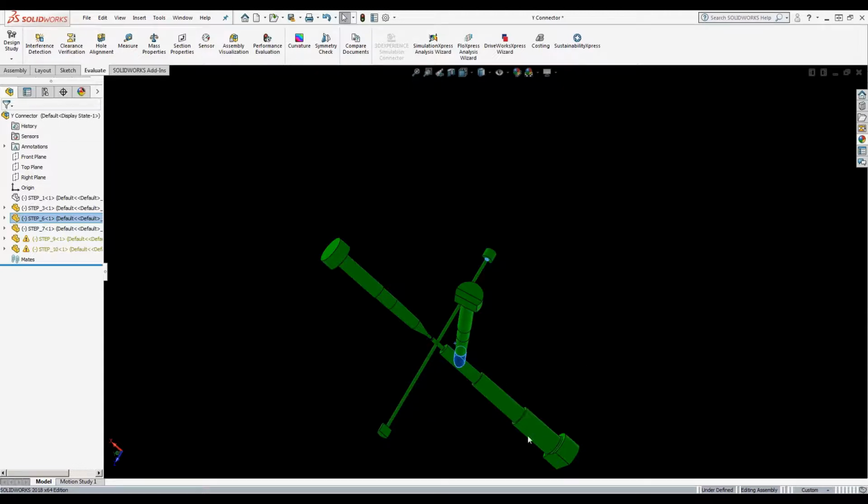There's more components to these, but they would all be pulled from the part after injection. And that's due to this being actual prototype tooling, quick turnaround. If this was a standard production mold, then yes, there would be some action on these, and they would open up as the tool opened to clear the holes before the part is ejected.